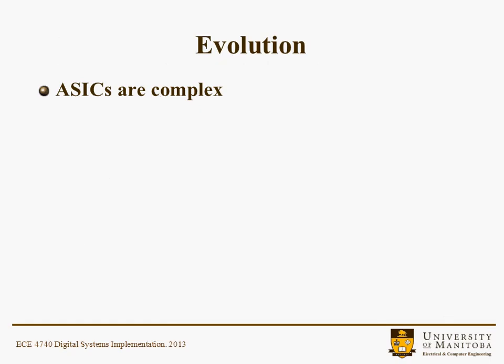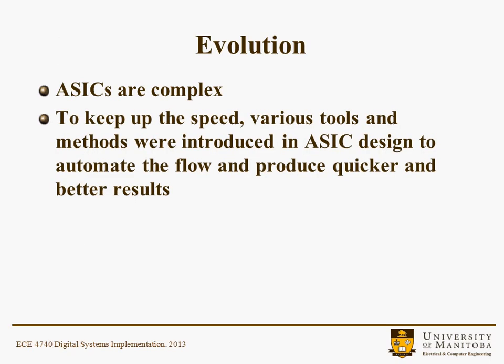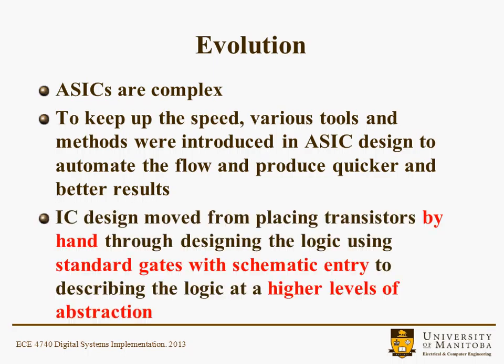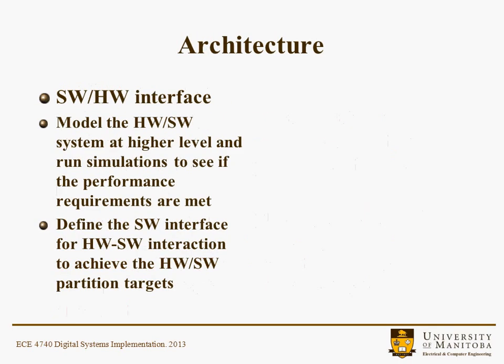ASICs are very complex devices, and through their evolution to keep up with speed, various tools and methods were introduced in ASIC design to automate the flow and produce quicker and better results. Better meaning more reliable, perhaps more testable, things of that nature. IC design moved from placing transistors by hand, so that's integrated circuit design, through to logic using standard gates with schematic entry, so that's something you may be familiar with, and much more recently to describing logic at high levels of abstraction, typically using a hardware description language.